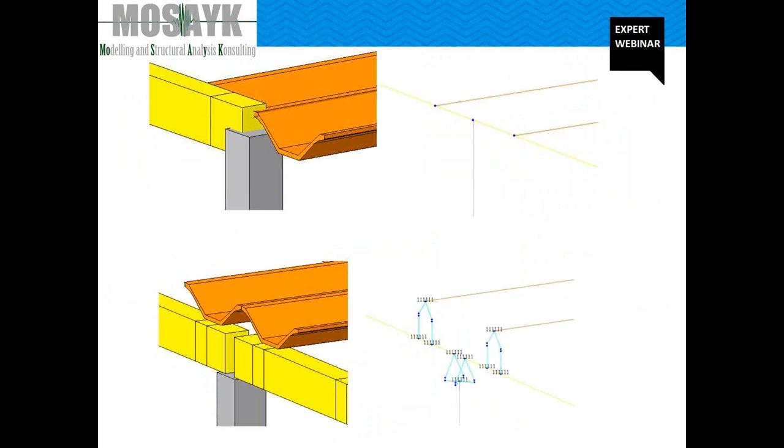Moving from a wall, stairwell, global building to a single local element, let us compare two different modeling techniques that can be used in Midas Gen. The first one, on the top, simply puts the beam and the roof center line on the top of the column. The second one, on the bottom, uses rigid links to put the real elements in the real position.